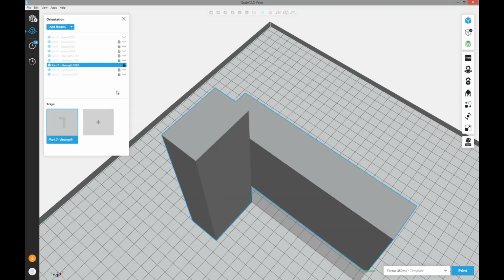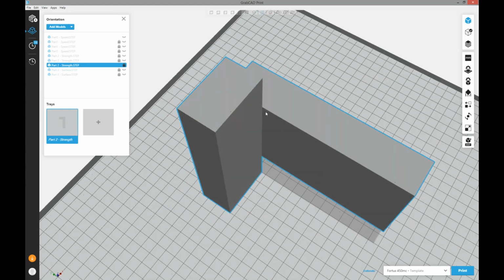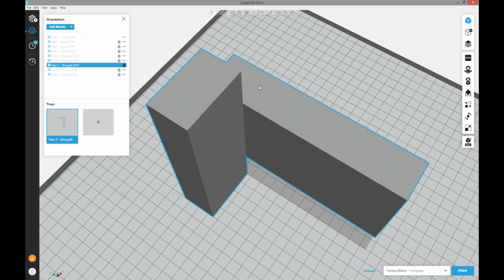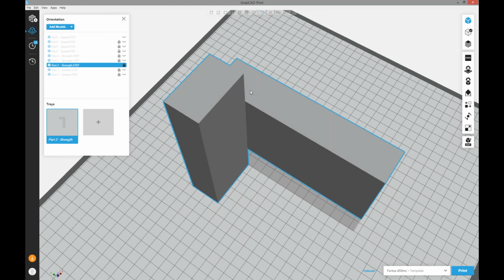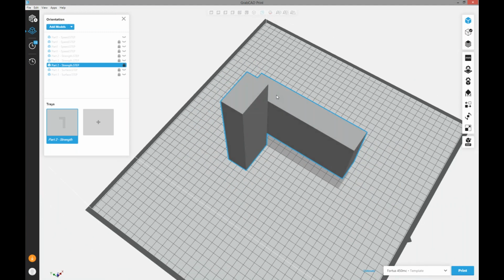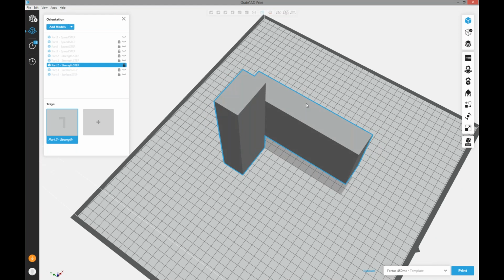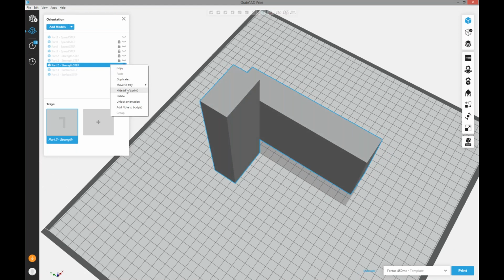A quick question from the audience, Carolus. Yes. There's a question if we can manipulate the contours or the seams within GrabCAD Print, like we can also do it with Insight. Yes, we can do that, we can increase or decrease the contours. We can change infills, and this is actually what I will be talking about in the third section by showing you advanced features on GrabCAD Print and how we can influence the part post-CAD designing. So I will be showing that. Make sure you tune in also for the third session. So this possibility exists. Thank you.